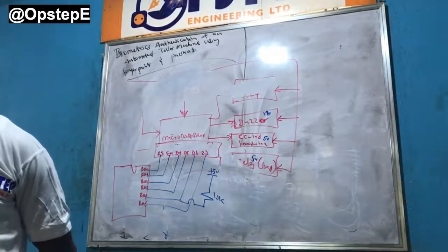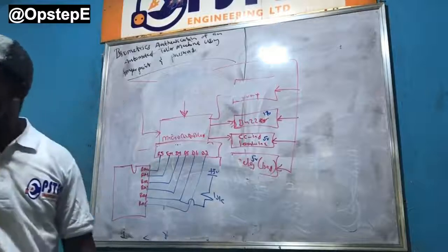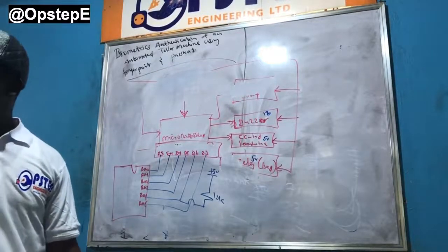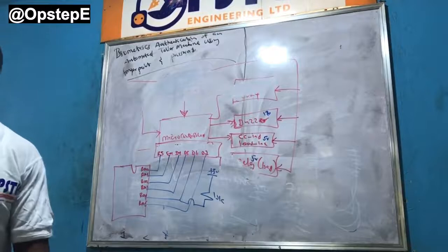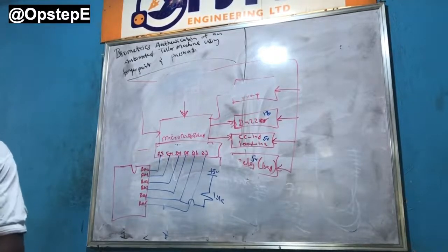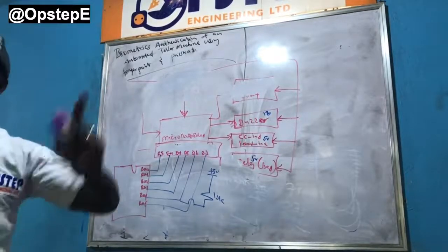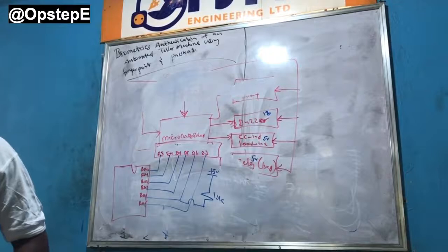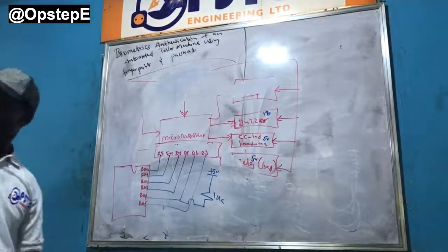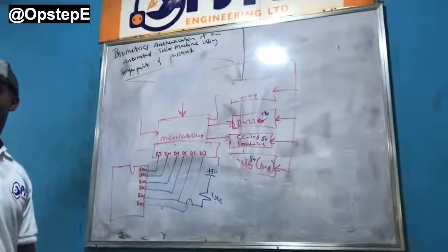That's how you call it active low. So will you not say that place is high all the time? No. It's only high when the switch is open. When the switch closes, it goes low. Except that this time, it is not taking the VDD straight to ground. It is taking it to ground through what? The resistor. You get it. That's exactly what's also going on. Can I continue?